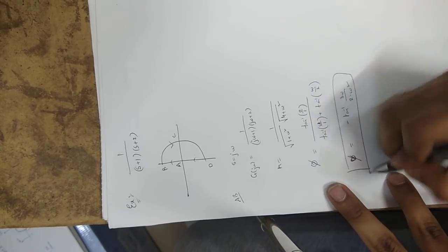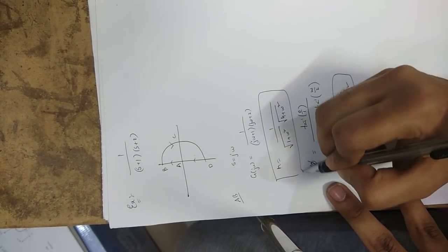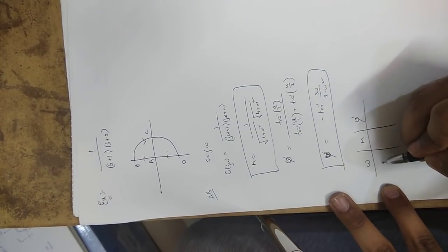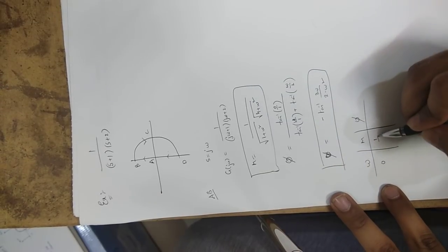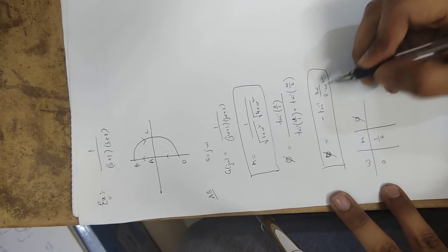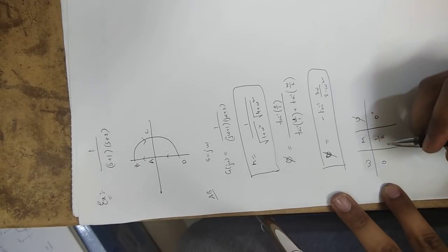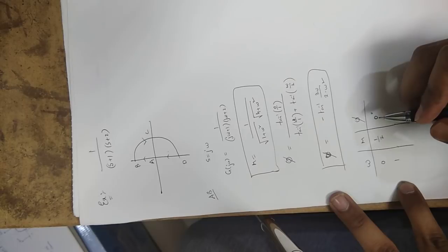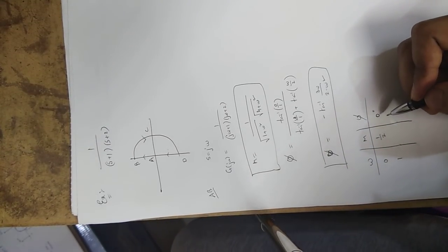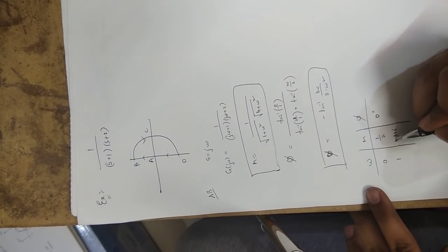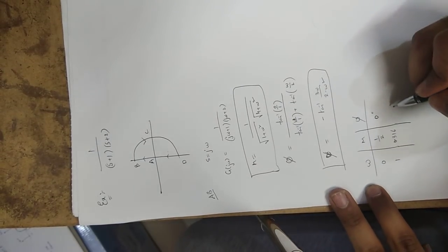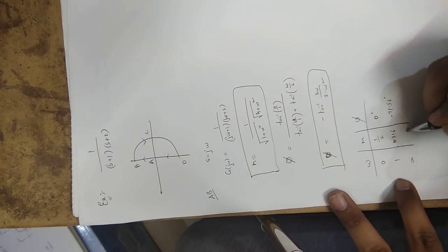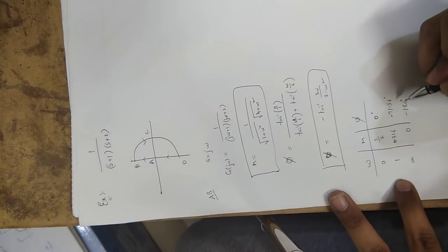So now you got phase expression, magnitude expression, varying the values of omega. Find out magnitude and phase. Let us say omega value 0, then you will get magnitude 1 by 2, phase 0 degrees. Let us say omega value 1, then after calculation we got magnitude 0.316, phase minus 71.56 degrees. Similarly, omega infinity you get magnitude 0, phase minus 180 degrees.